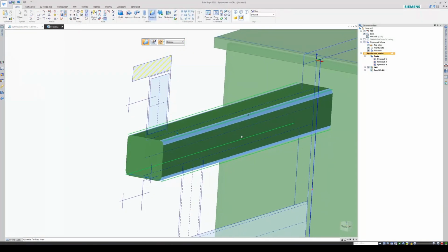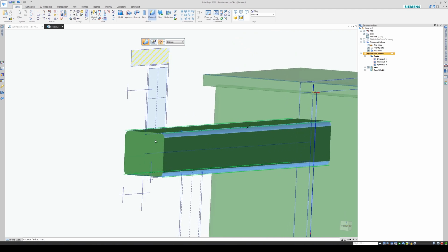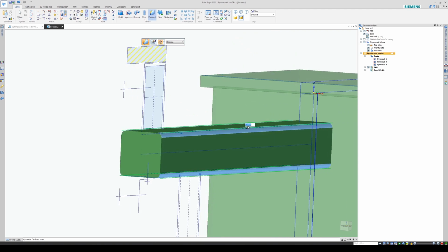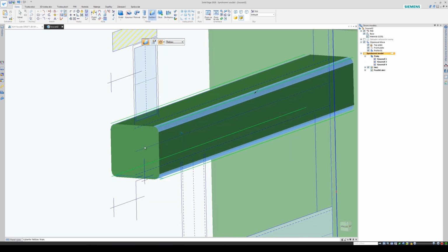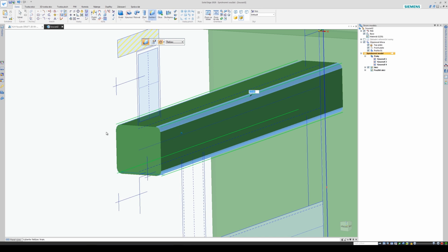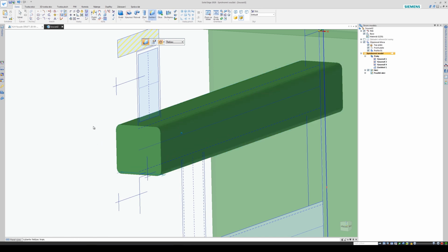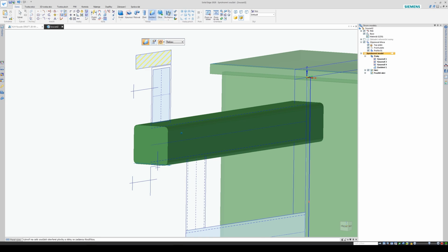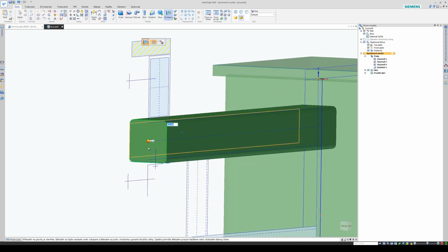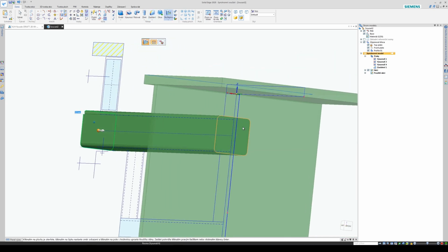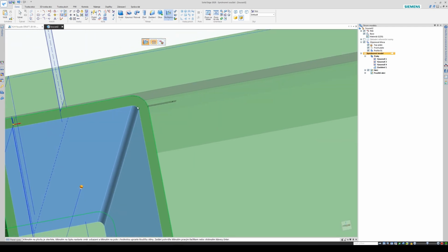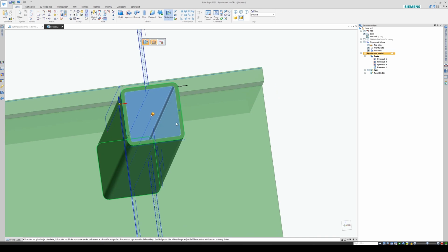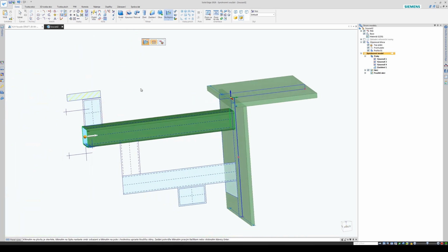It's 8 millimeters minus 5 millimeters, the wall thickness. The inside radius, sorry, will be 3 millimeters. That's okay, that's reasonable. Okay, so like this, and then thin wall. Remove this face and this one. Okay, and here we have inside the nice radius, 3 millimeters,